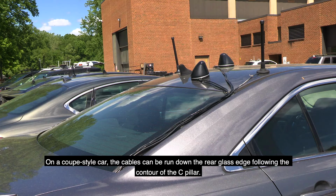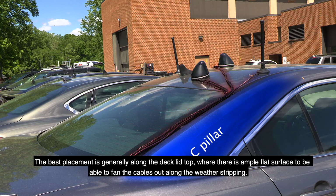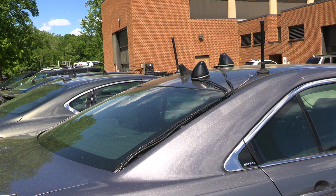On a coupe-style car, the cables can be run down the rear glass edge following the contour of the C-pillar. The best placement is generally along the deck lid top, where there is an ample flat surface to be able to fan the cables out along the weather stripping.